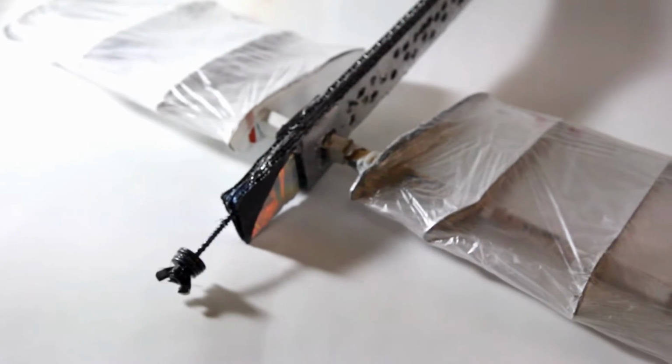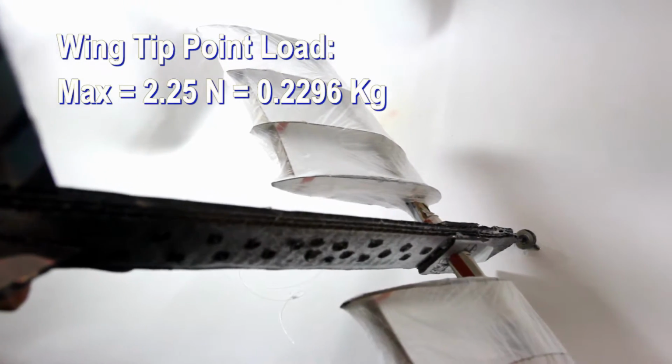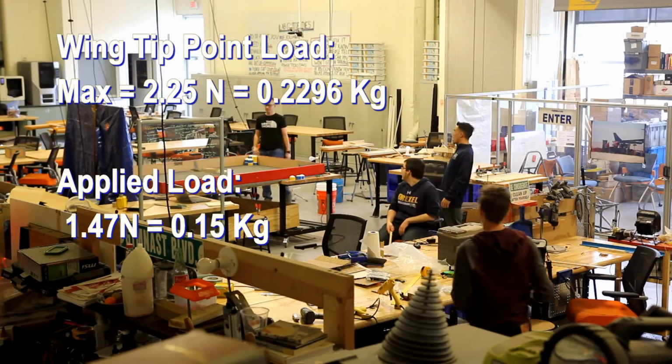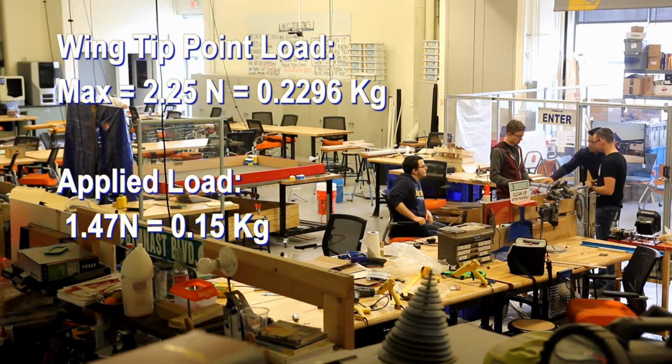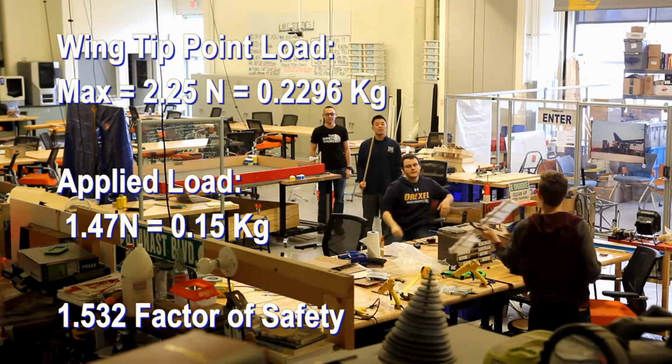The final design of using an equilateral triangle cross-section for our cardboard wing core is rated to support a maximum of 2.25 newtons, or equivalently 0.2296 kilograms. The provided test load of 0.15 kilograms has a final design factor of safety of just over 1.5.